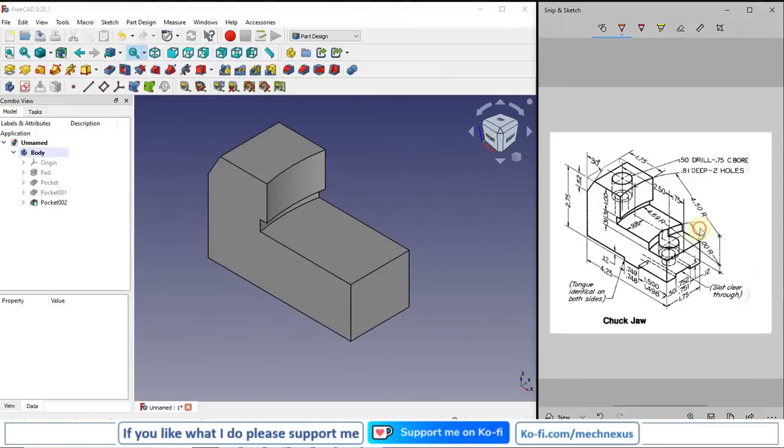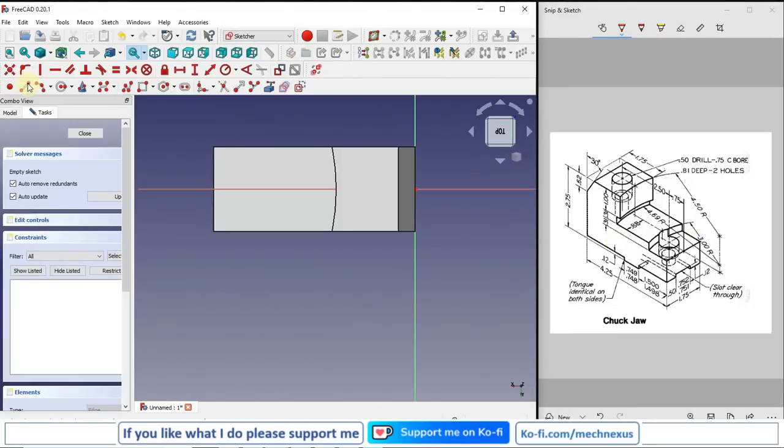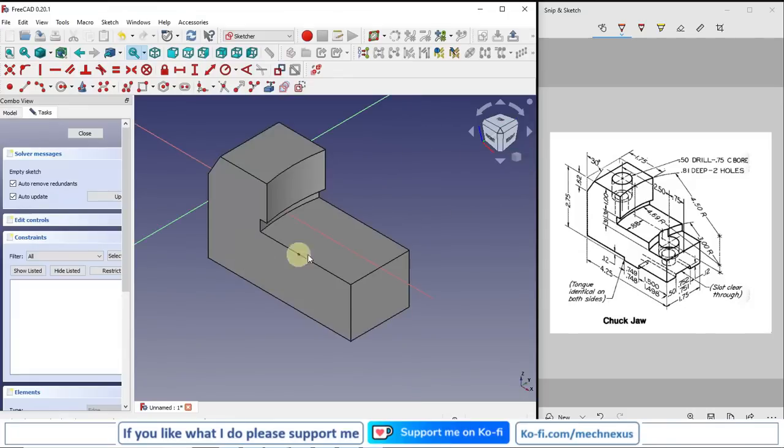Now we will make this radial cut here on our new surface, so I will select this face and I will say sketch. Now in the same way I will project these two edges, and now I will go for the 3-point arc, and I will coincide my arc center point with my axis, and then I will give radius which is 3 inch.